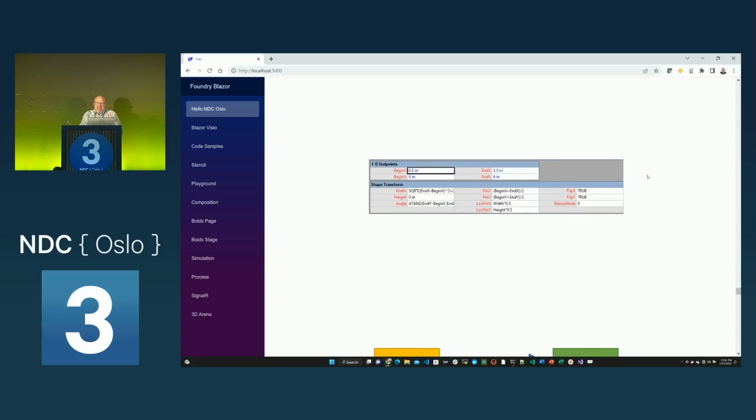Now this is how Visio defined a 1D shape. What's different about a 1D shape than a 2D shape is it's given these two extra parameters here, the beginning and the end. And that's where you would attach and glue. That's how it calculates something. But you notice that it has formulas now for the pin X and pin Y, which is the center of where those 2 points are.